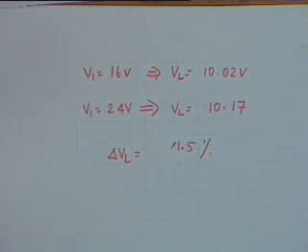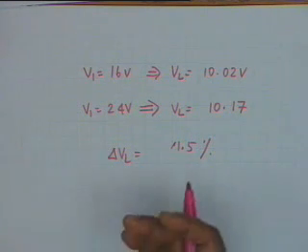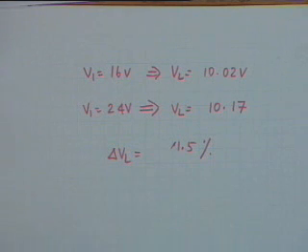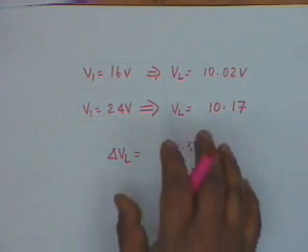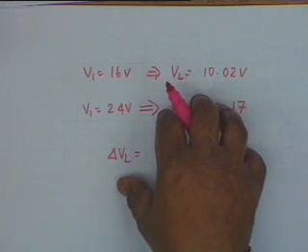And this is the most common method of voltage regulation, the simplest and the most common method, used in instrumentation, used in all kinds of applications. Unfortunately, very high voltage Zeners are not available, and therefore this kind of regulation is limited to low voltage only.